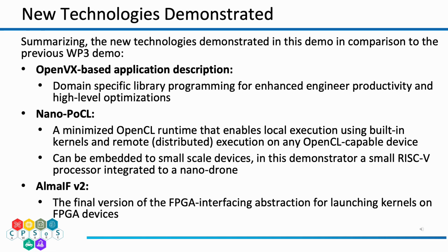We also demonstrate Nano-PoCL, an OpenCL runtime tailored for low-end devices, such as a simple RISC-V-based processor in this demonstrator. The final version of the ALMA-IF version 2 is demonstrated with built-in kernel abstraction for launching kernels on FPGA devices from the drone. Flexibility and robustness of the ALMA-IF has been improved from the last demonstrator. It has also been open-sourced as part of PoCL.